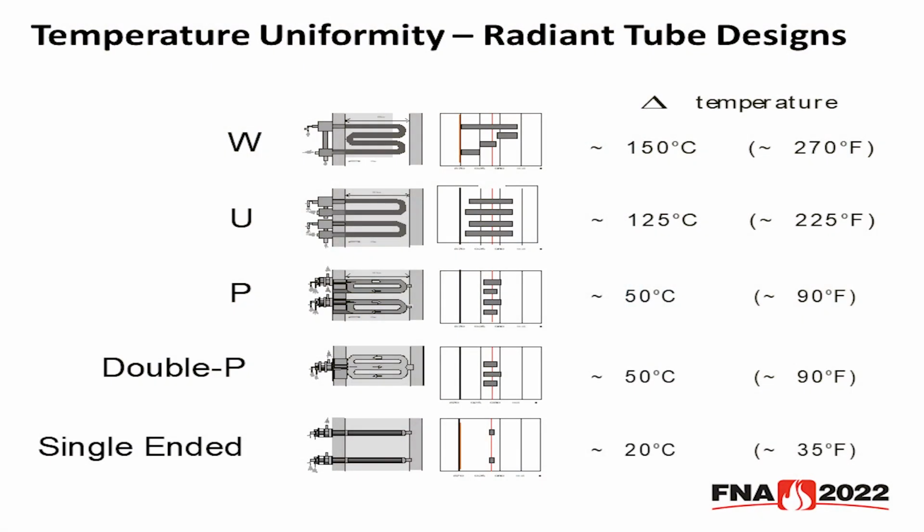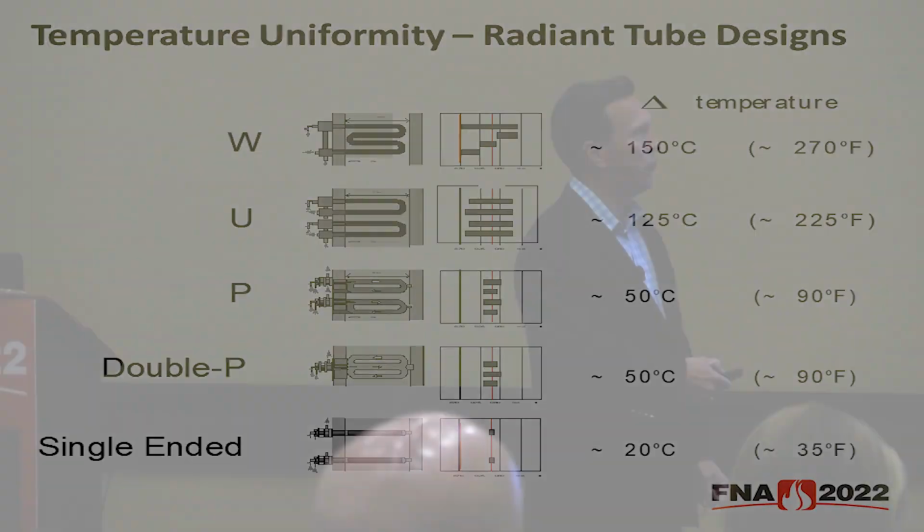This graph represents some experimentation conducted in our laboratory in Germany. They tested various tube types, non-recirculating versus recirculating. They placed thermocouples on each leg of each tube, approximately 6 inches apart, and they were looking for the maximum temperature gradient.